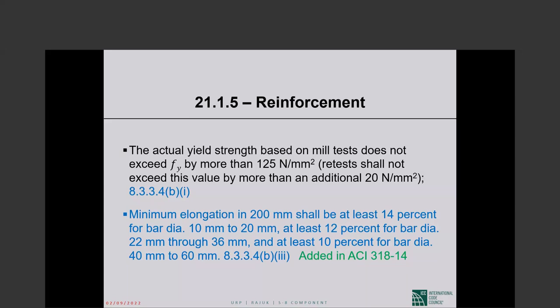And that came up with the load combinations with overstrength factor yesterday. You just cannot use it when you like and make members stronger. That may very well be to the detriment of your structure. So this is when the yield strength of your reinforcement is significantly higher than what you specified. The flexural strength of the member reinforced with that steel will be higher than you figured.